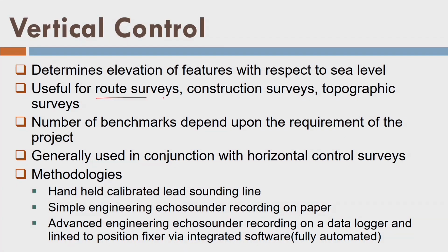It is very useful for route surveys, construction surveys and topographic surveys. So, we establish the number of benchmarks depending upon the requirement of the project. It is always in conjunction with the horizontal survey. We do not separate the horizontal and vertical survey.